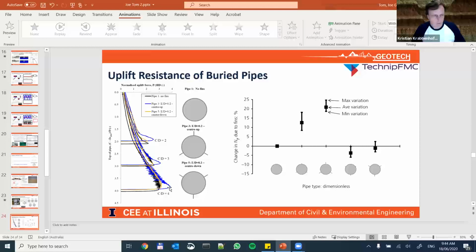Sure, great. Just one comment on that. In OPTUM, there's a model called GSK, which is kind of a nonlinear Mohr-Coulomb envelope. And there's the Bolton model as well, from Bolton's 1986 paper, I believe. But the GSK model is similar, and I think it matches experimental data a little bit better than Bolton.